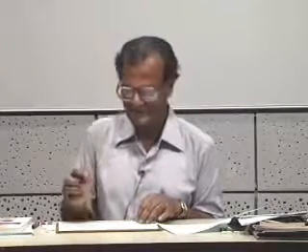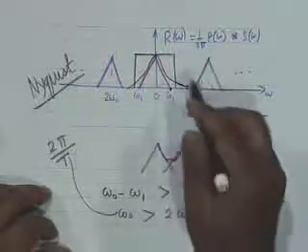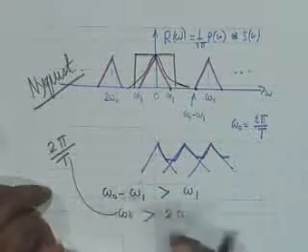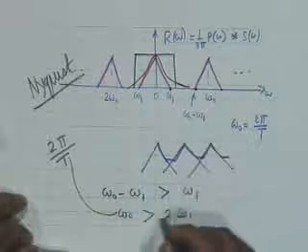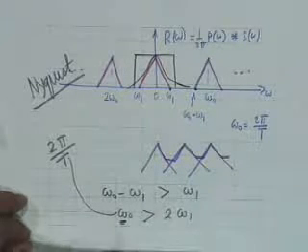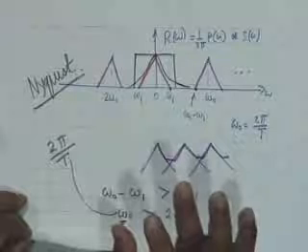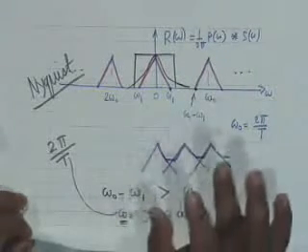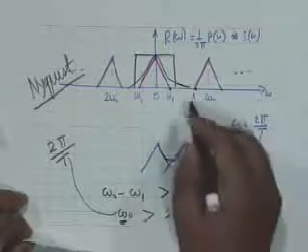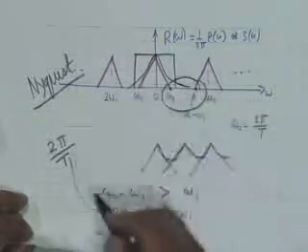1.4 kilohertz. Okay, this safety margin is allowed so that the trailing end becomes negligible. In other words, you can approximate this by means of a triangle. All right. So this is why omega 0 is usually kept greater than 2 omega 1, not exactly 2 omega 1. In theory, this is possible, but in practice, since no signal is band limited, it is required that there be what is called a guard band.